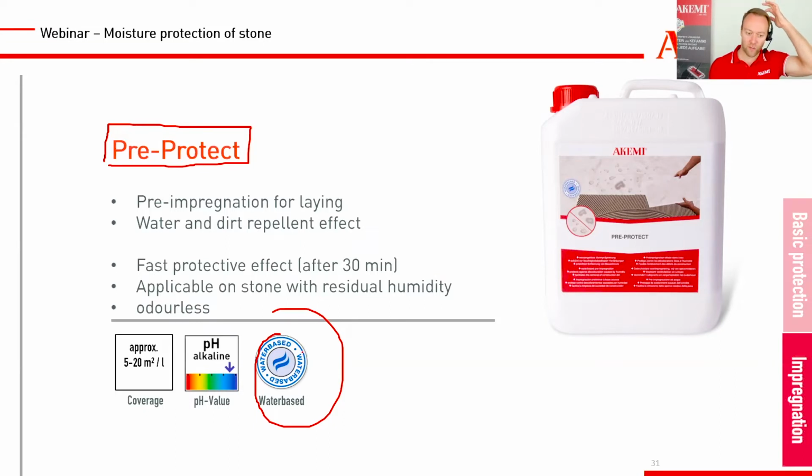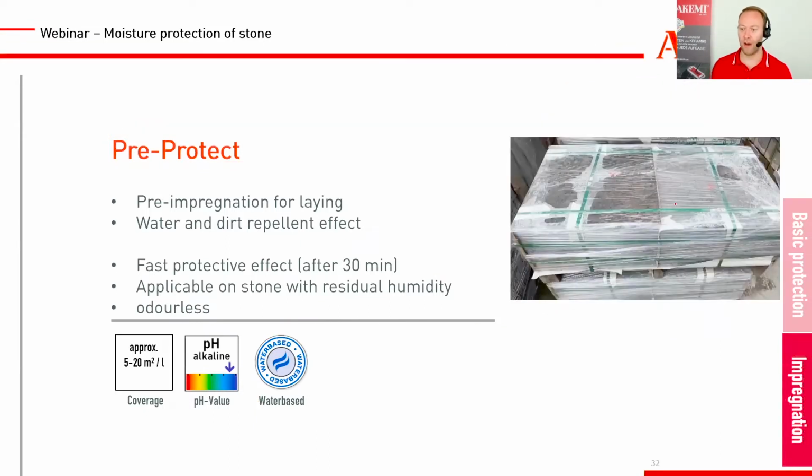So what is the advantage of a water-based product? It can be applied also on stones which still have some remaining humidity, because how is it usually on the construction site? You get your stones delivered. Sometimes they are wrapped in plastic, but even if they are not, they can have some trapped moisture inside. And this doesn't matter because the Pre-Protect is water-based, so you can also apply it on some humid stones. And after 30 minutes of application, the stone is already finished and protected, and you can start laying the